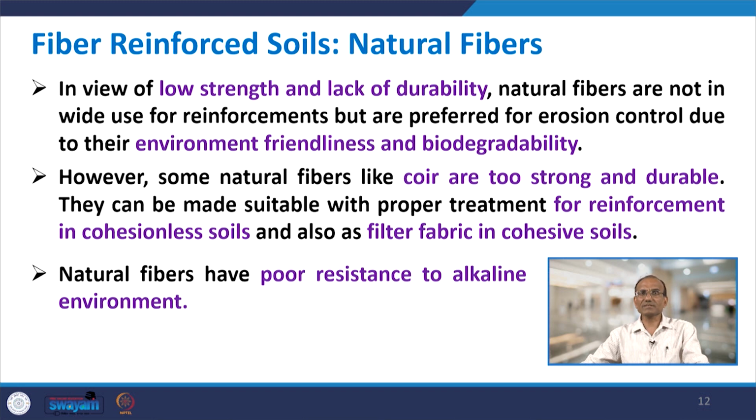However, some natural fibers like coir fibers are strong and durable, so durability is not an issue. They can be made suitable with proper treatment for reinforcement in cohesionless soils and also as filter fabric in cohesive soils. Natural fibers have poor resistance to alkaline environment. In fact, for one of the natural fibers, coir fiber from coconut, we are going to discuss a case study in the next slides, where it worked excellently, particularly for liquefaction mitigation.